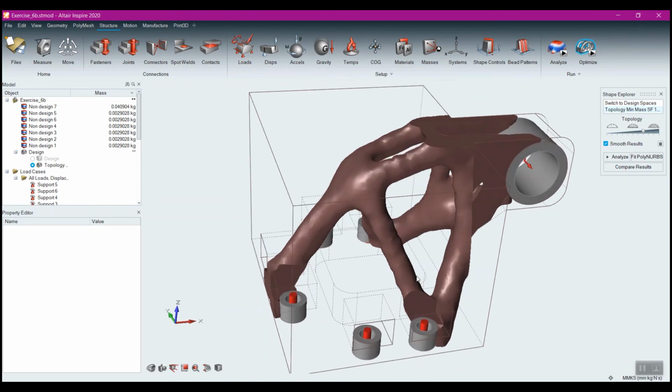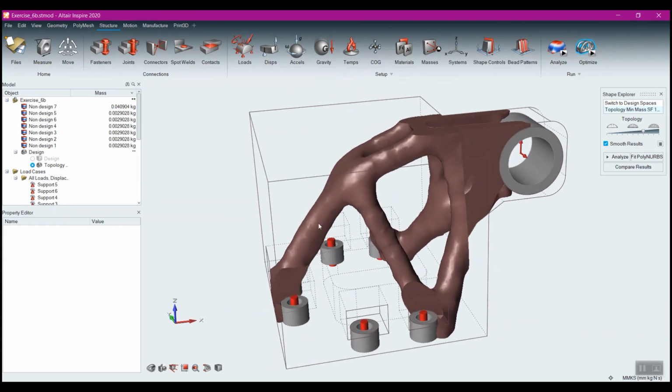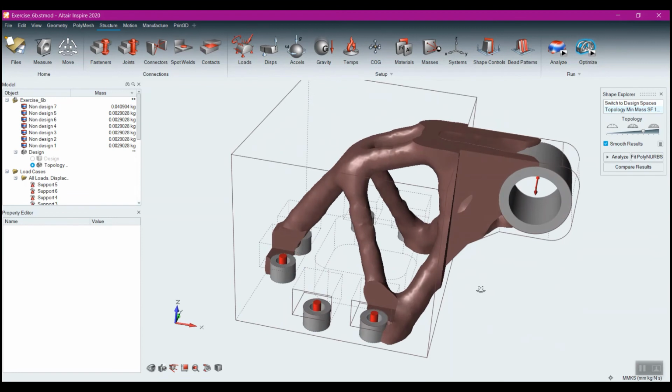And again, this is why I say we're not designing the part for you. Maybe this is an aircraft part. Maybe the FAA requires that all aircraft door hinge brackets be attached in 6 locations. You're not going to turn to the FAA and say, well, no, the optimization says they're not necessary, which is true. They're not from a stress standpoint. But from a redundancy standpoint, we may want it there. So you're going to engineer in some result. And we don't have to rely upon the optimization code to give us that result. We would engineer this from us.